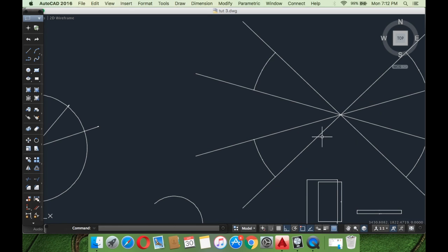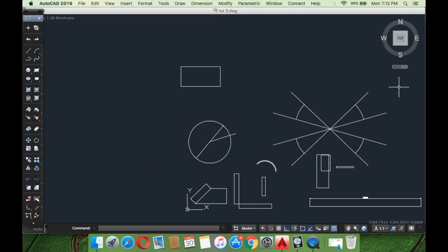These are not continuous lines, and it's pretty complicated because AutoCAD can't figure out which line to join with what, and these are dimension lines, so it cannot join. So you can see that these two lines have been joined. And suppose you have done that, what you do is you select the whole thing and press explode. If you want to do that, the whole thing gets exploded.